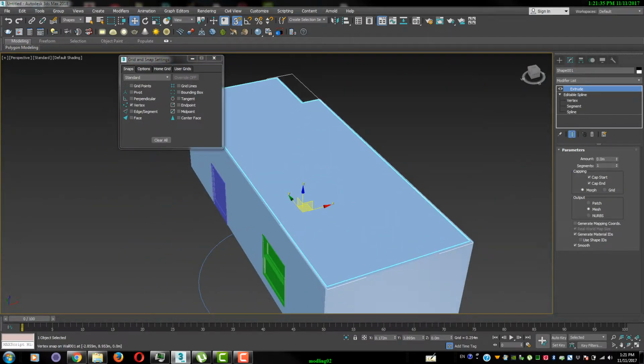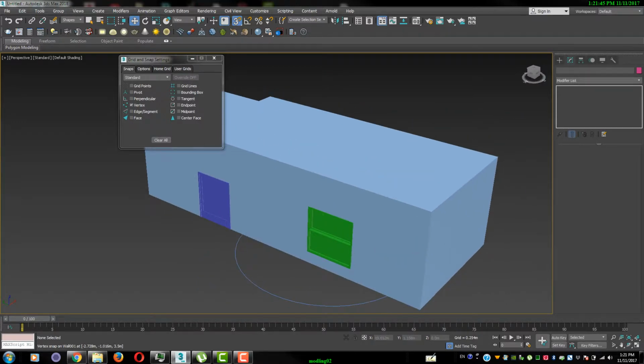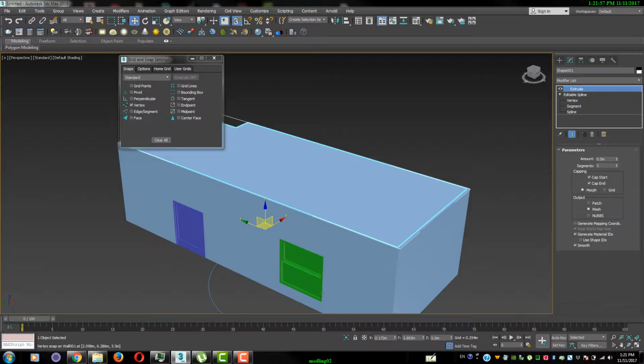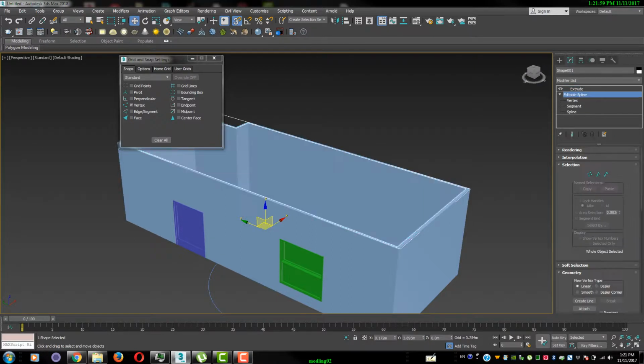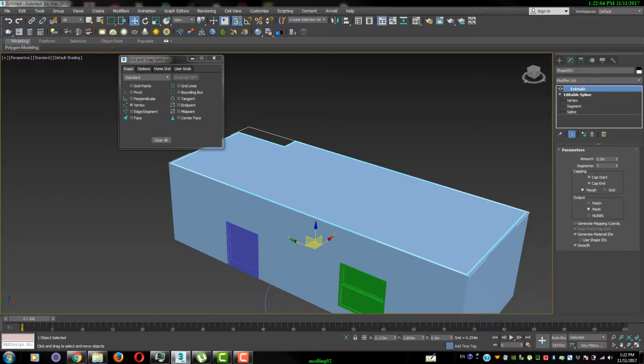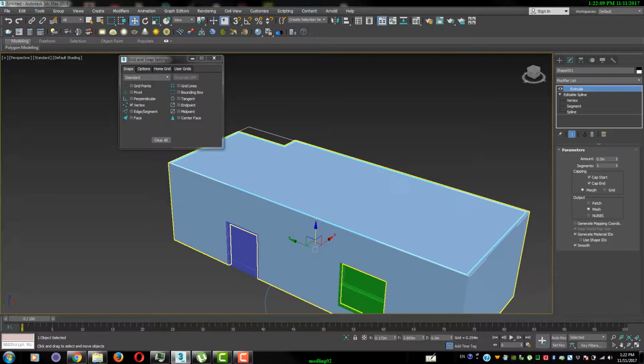Also, I want to go to shape. Okay. This shape, now because I used the modify, edit, extrude, the mouse can't feel shapes now because it was converted to 3D geometry. So I go to all, I select again. I want the spline line, this spline line, I want it duplicated. Shift, I want to turn off my snap.